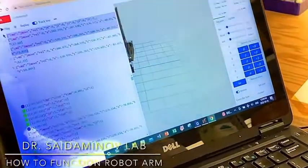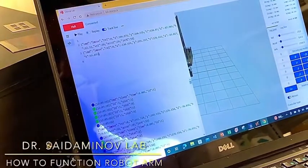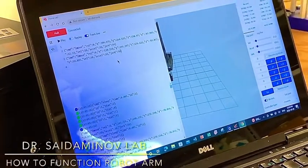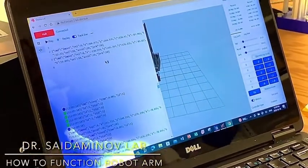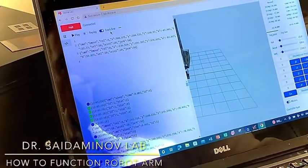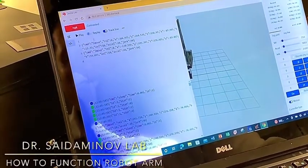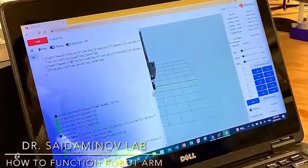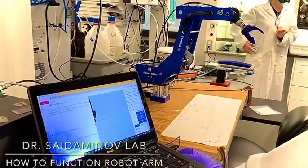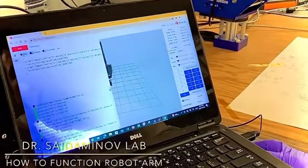Here, the previous code should be deleted, and I have two positions. I'm going to give some acceleration, jerk, and velocity to say with what speed it should go. And then I can even turn on the track line to see which code lines are running by Dorna 2, and I can even turn on the replay. It can go back and forth. I gave a very small amount for velocity because if I made a mistake, I don't want to hit something with the robot arm. Then I can play it.